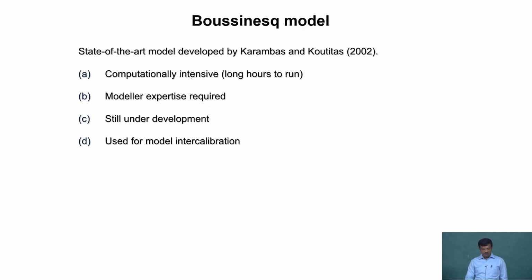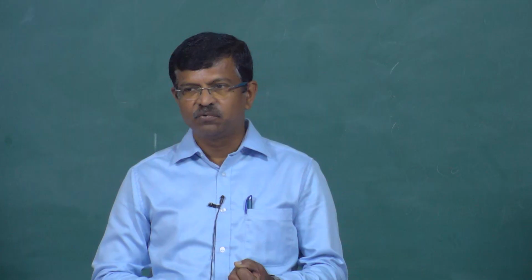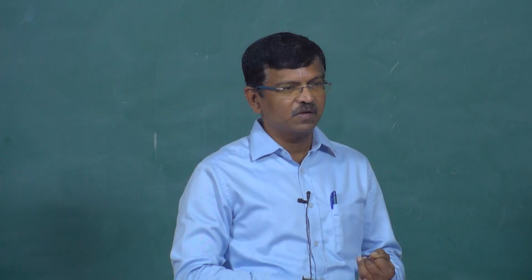Okay. And finally, on the Boussinesq model, I am not sure whether Professor Zhang is covering it or not, but the Boussinesq model is another comprehensive model. It is a complex system and a combination of the so-called short wave and long wave, and we can tune on either side. I can work for short waves with the Boussinesq model, I can work with the long wave with the Boussinesq model, and those who are working with the long wave never bother about short wave parts, and vice versa. The Boussinesq model is very complex and takes care of wave breaking and many aspects that cannot be taken by most of the phase resolving models in a full form, and we can tune the Boussinesq model for wave breaking.